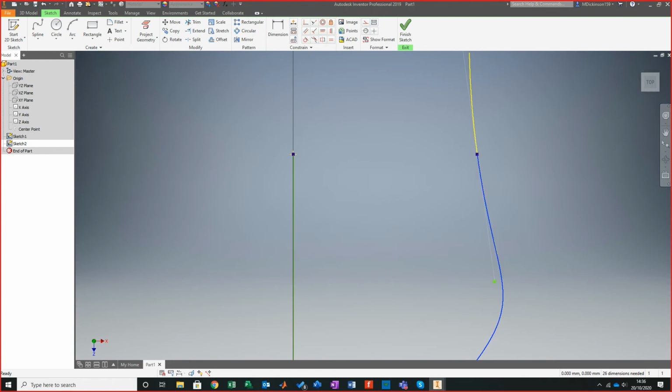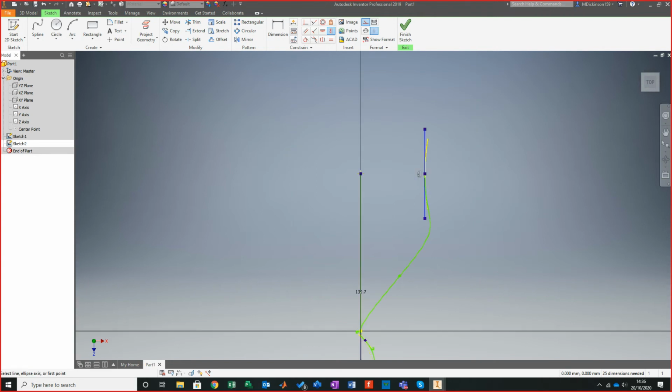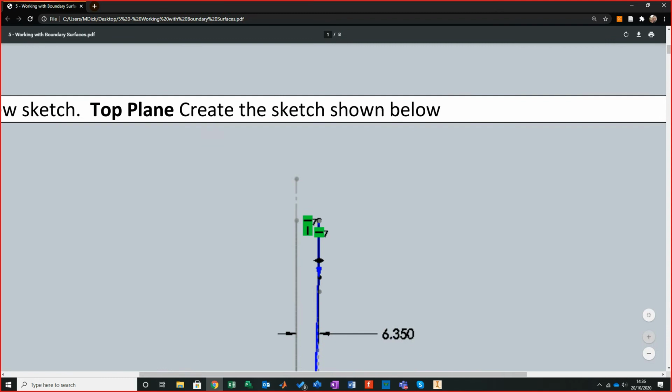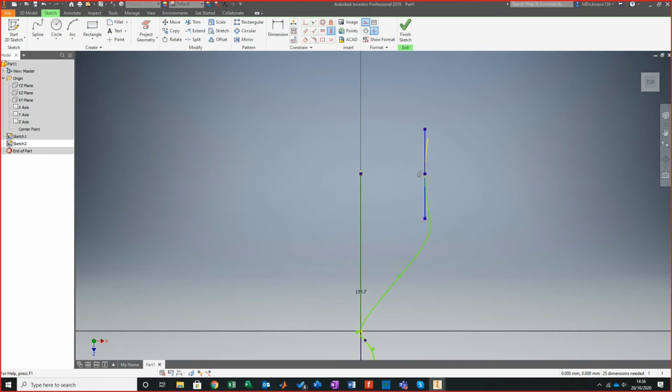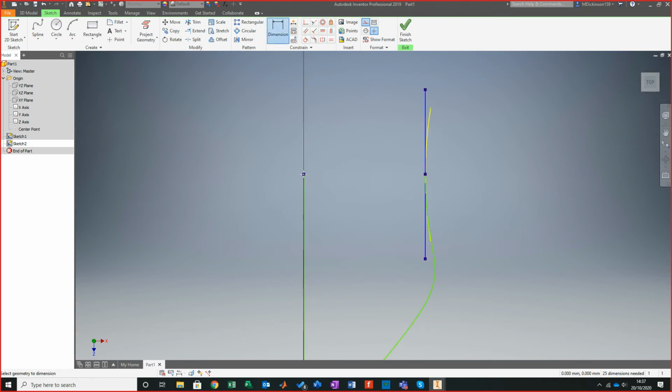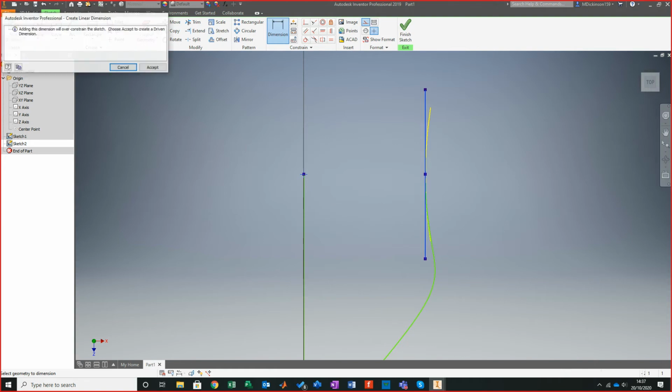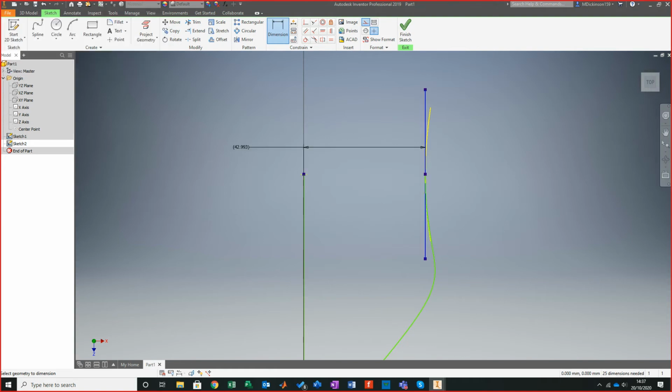And now what I'm going to try and do is make this one vertical. Now the reason I'm doing that is we have horizontal between these two and we have a vertical, and then this handle is restrained to 6.35 millimeters. So I come back in again using that point, then coming from here, and I can go, except yeah, it's not happy with that.